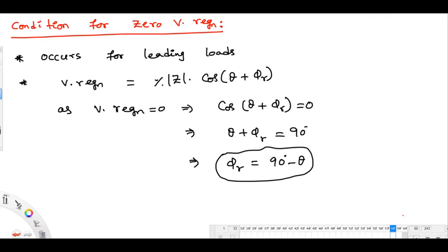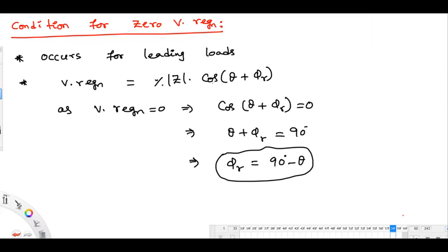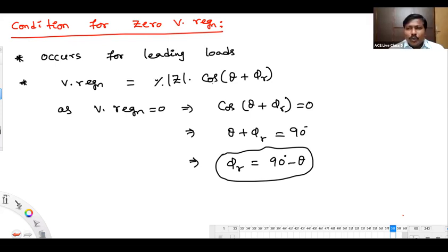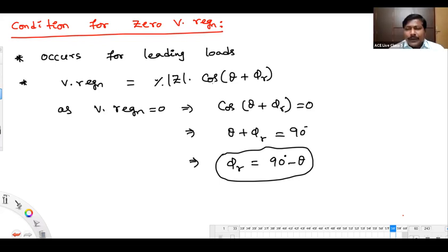Yes, but the left side C by 2 is referred to Vs and the right side one is referred to Vr. If you want, you can move that C by 2 to the node where you are taking. Then the resultant nodes will be 2 only, right? And if you have zero impedance between any 2 nodes, will you consider that as a single node or 2 nodes?